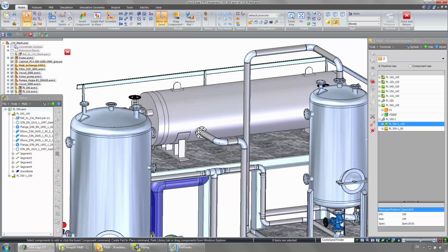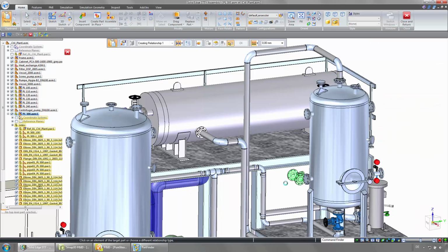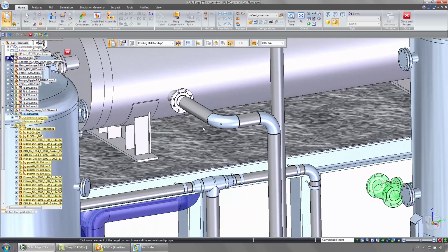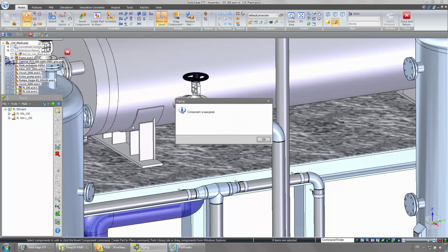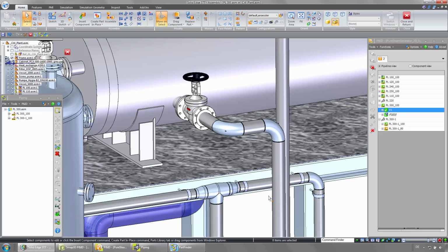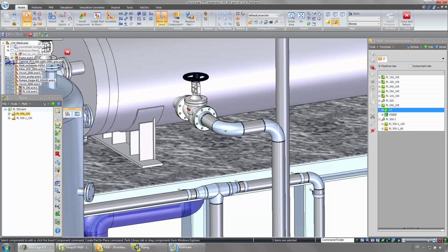The necessary valve is interactively placed via the to-do list. For placing the valve to the pipe, the native Solid Edge and Mate functions are used. Hereinafter, recalculating the pipeline causes an automatic placement of flanges and gaskets at the valve.